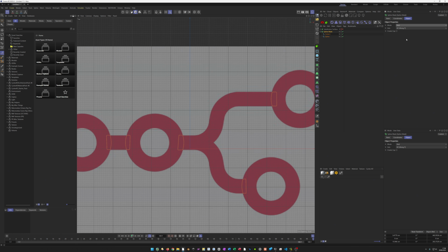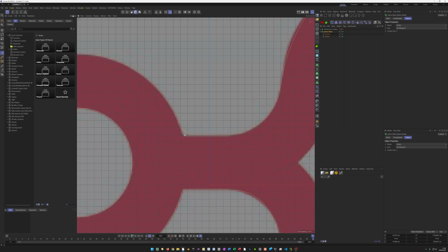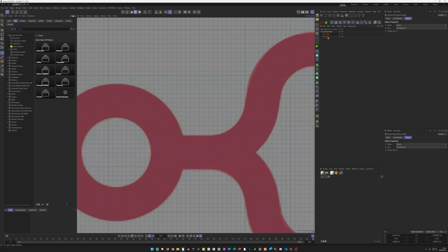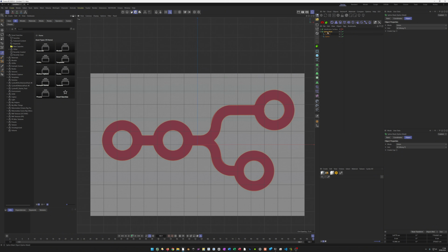When we go to end, we get something like this. Just the overlaps. That is not what we want. Intersection is not what we want. A subtract B is not what we want. B subtract A is still not what we want. So union is exactly what we want. And you see we don't have nice things here, but that doesn't really matter. We can change this later on. Let's say I am happy with this.